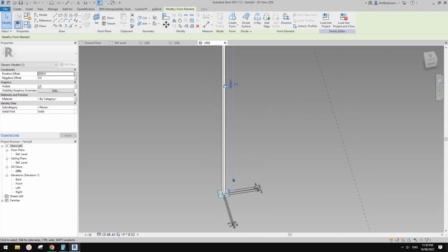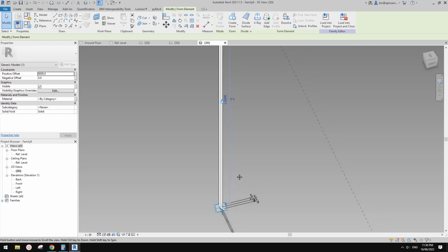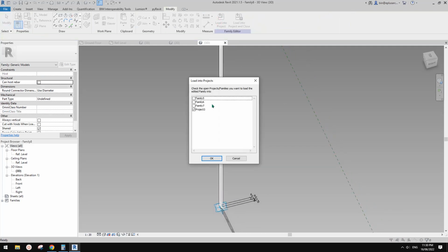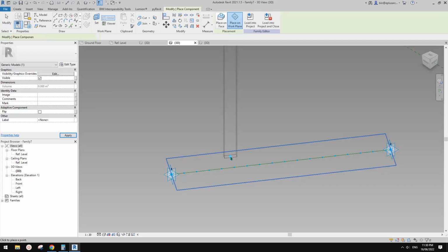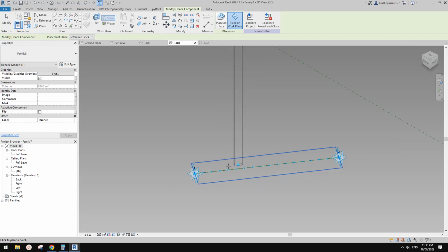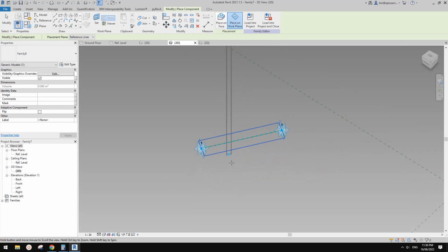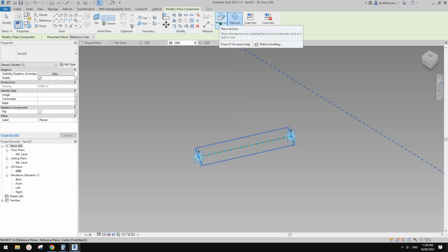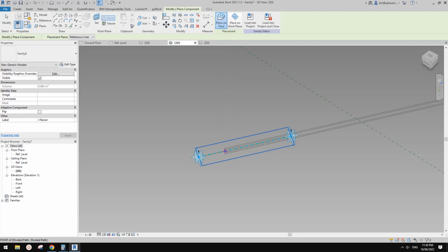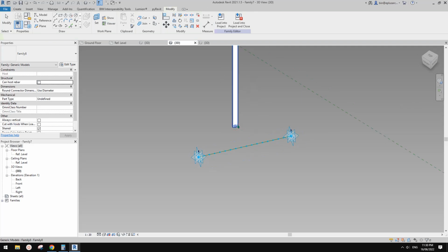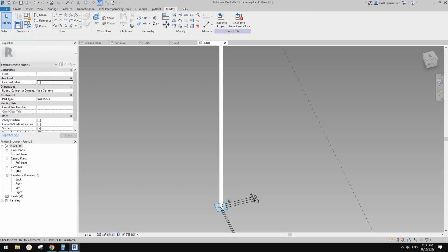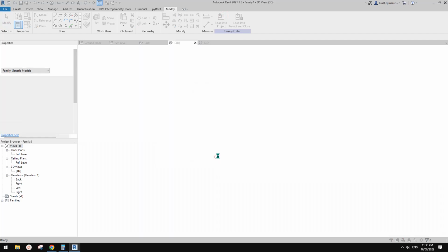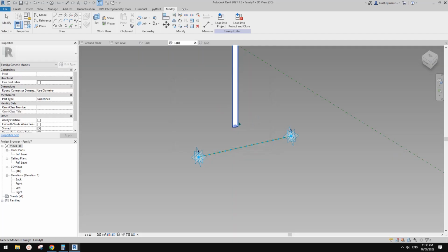This is an adaptive version of batten. Okay, so load this back into this one, I think. Adaptive family. So we can try to place it onto, just make sure you need to use place on face. Okay. Whoop. Wrong direction. That's fine. So let's just select it, edit family, go back here, check the box, always vertical. Load this back, overwrite, and I'll just